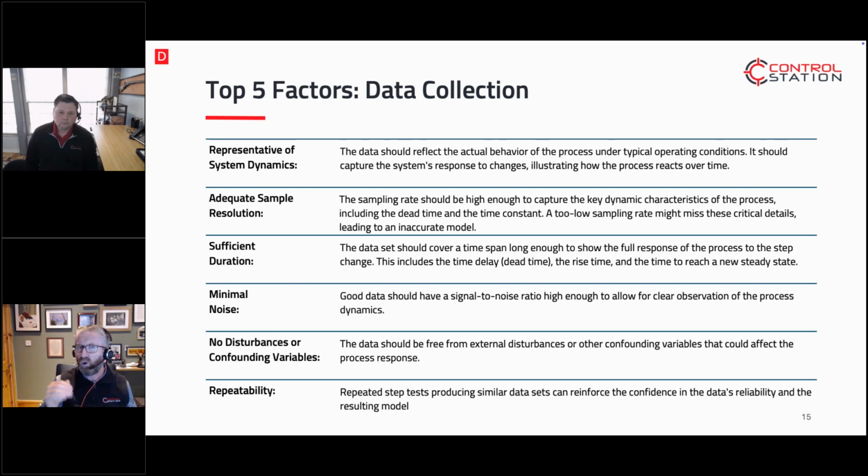Can we just tune that a bit more aggressive to stop those spikes there? But if those spikes are process noise or instrument noise generated, it's going to be very hard to get them tuned out, and it can cause you to push the aggressiveness up that curve to a point where you're tipping on the edge of trying to be responsive when you're not actually doing it. Disturbances and confounding variables. Bob, do you want to jump in on those confounding variables?